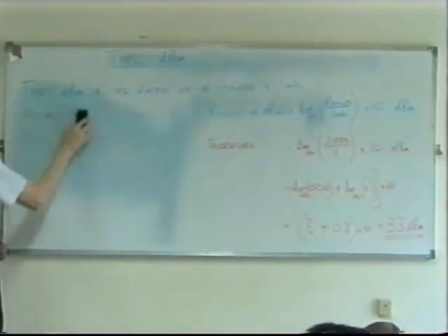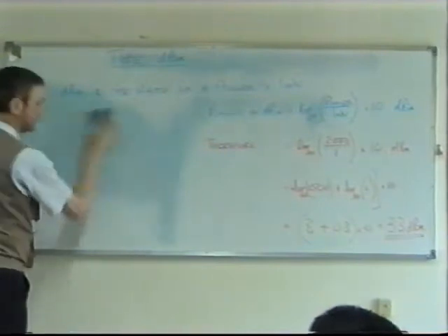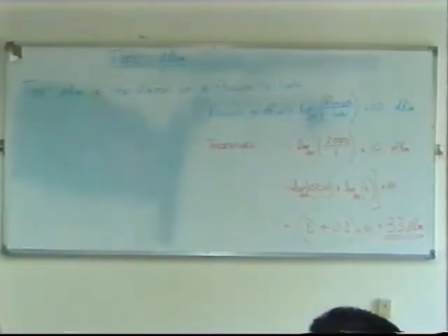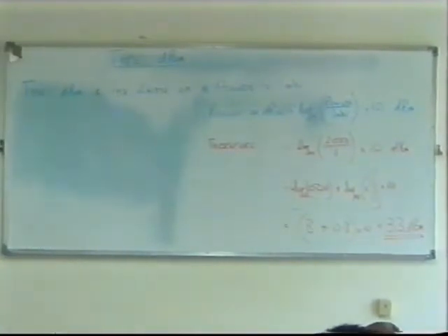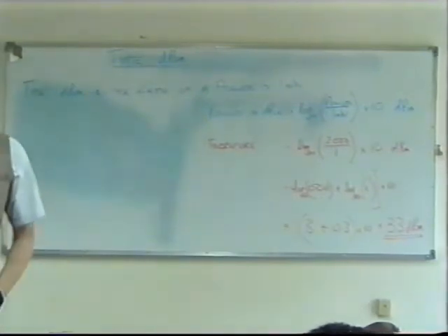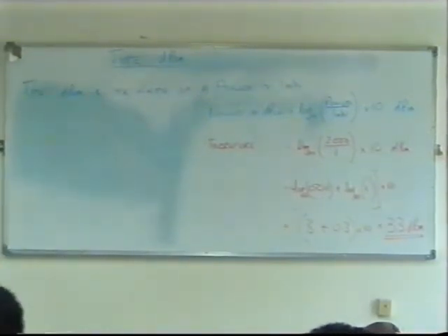Right. Now, the question I'm asking is, and this is just an example, but it's a good example: if you double the power at the output of an amplifier, let's say an audio amplifier with a speaker, and you double the power, let's say it was 100 watts, you double it to 200 watts. You add 0.3. 0.3 times 10, 3 decibels. Exactly. It's a 3 dB change. That's all, 3 dB.